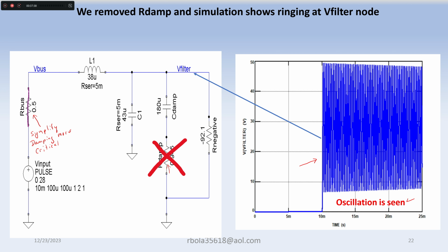So in this case, you do a transient response, which is basically a step function, and you can see that as you step, it starts oscillating at 39.34 hertz, which is very interesting.